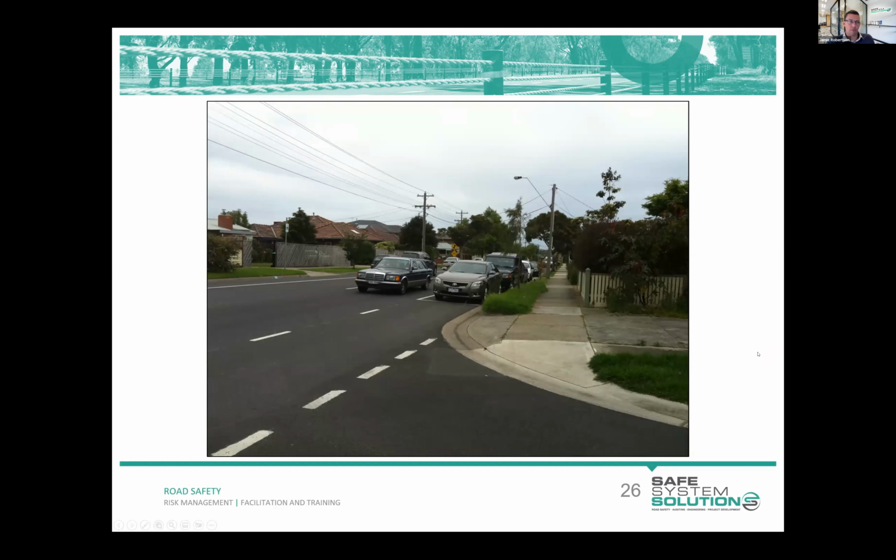That's a great question. If we do introduce a curb outstand, we need to make sure that we're not squeezing up cyclists if they're present. If there's a bike lane, we need to maintain a width for cyclists past that outstand. It is sometimes the case that we construct an outstand, like so, and the result is that cyclists are sort of funneled into the traffic lane, and we create a potential conflict there. So, an important consideration.